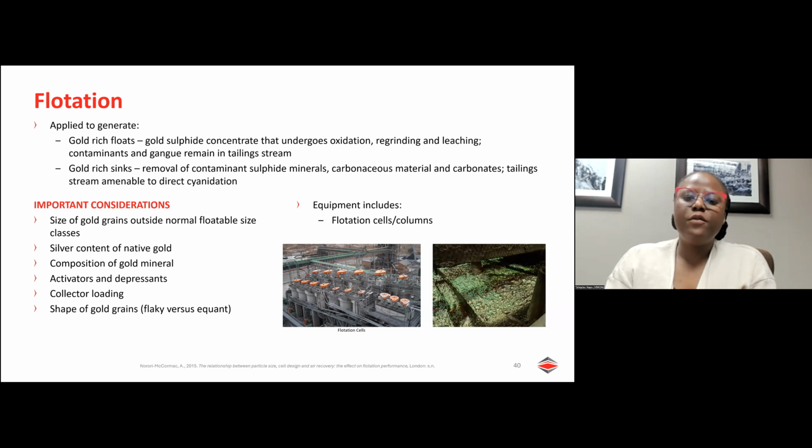Then if your main minerals within your stream are gold sulfides or arsenides or tellurides, then flotation is going to concentrate your stream in the floats, because your main mineral is maybe a telluride or arsenide. And this will then leave your contaminants behind in the flotation tanks.